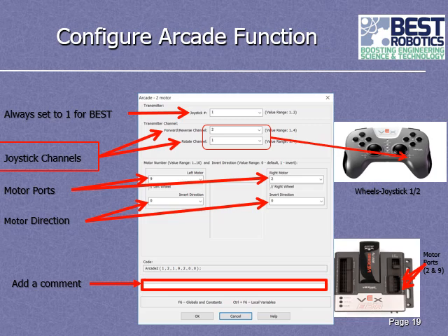The next thing we're going to have to do is pick what ports your motors are attached to. And this should match what you designed earlier and put in that configuration pop-up. So when you hit the drop down for the left motor, you'll see something that says left wheel, so you just pick that, and it happens to be the description for motor port 9.